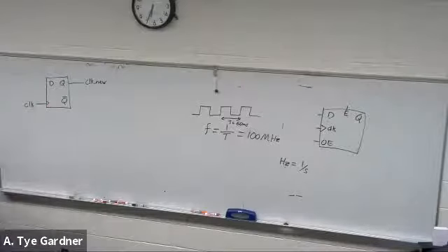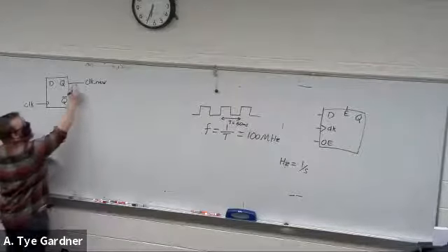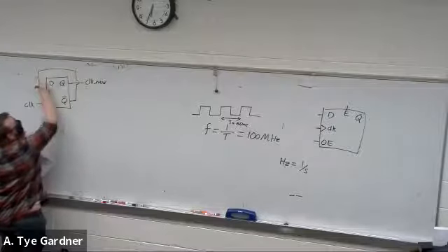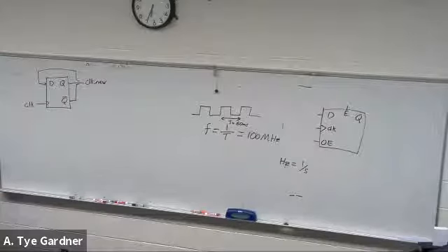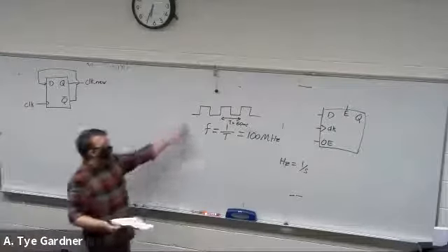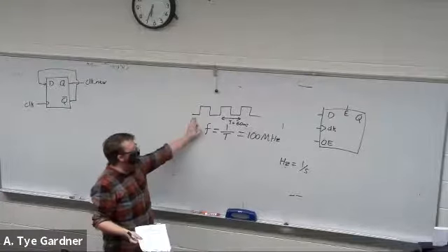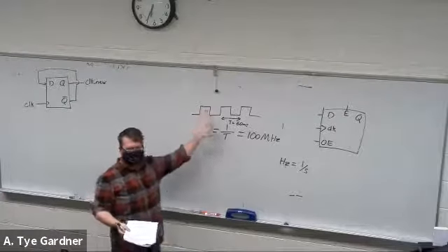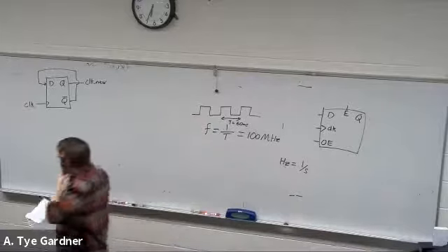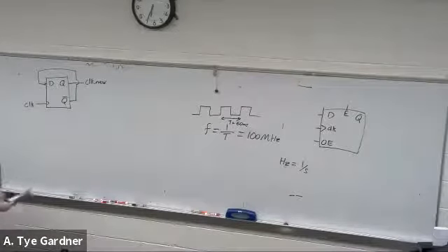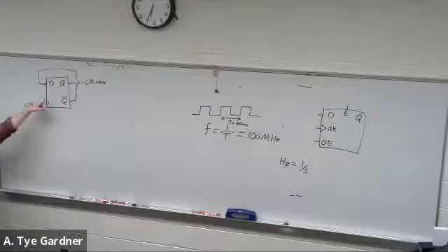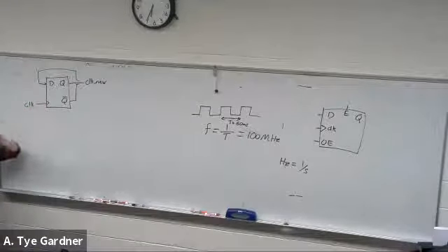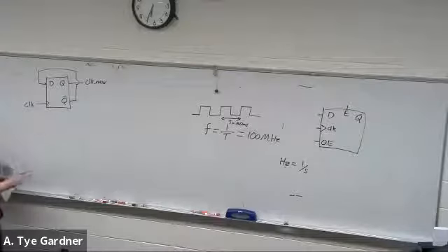Well, it turns out a really easy way to do that with clocks is just take not clock, right? Because that's all a clock doing is after every amount of time, we say clock is not clock, just up and down, up and down, up and down. Cool. So that's what this is doing, is every time a clock edge hits, the new clock, Q, becomes Q bar. Okay, so what does this look like?